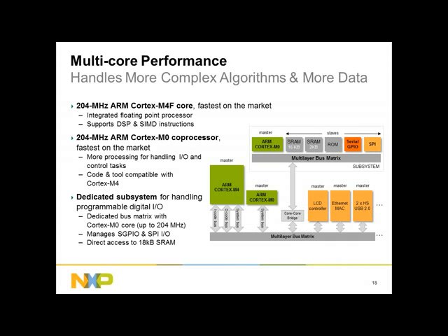We have an app note that's interesting. It uses the serial GPIO as a VGA camera input. Obviously, using this M0 core for the VGA camera input, you're using most of the bandwidth of the new M0, but you can actually get 30 frames per second VGA camera input using serial GPIO. So there are a lot of flexible, kind of cool things you can do with that peripheral.